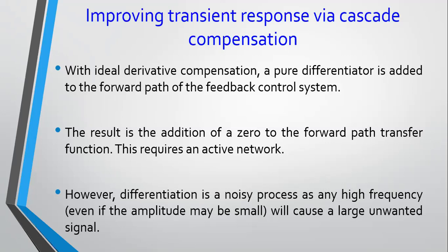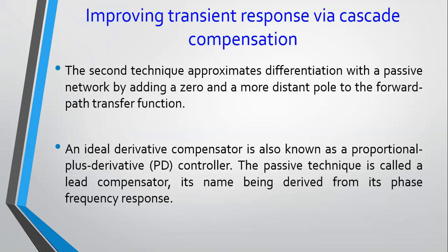Okay. So we know when we actually differentiate a signal, differentiation is basically differentiating with respect to time. So if you have a very small change in the amplitude of a signal over a small amount of time, even if that change is quite small, if it occurs over a small period of time, that can be amplified by differentiation. So we have to be careful when we are using pure differentiation. When you're designing the PD controller, it can introduce noise in our process.